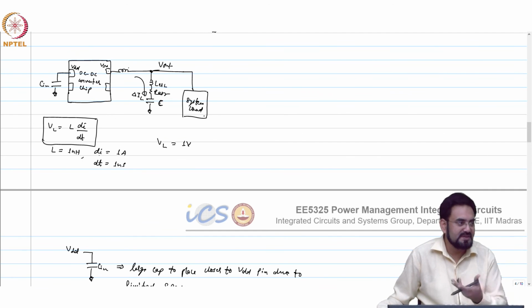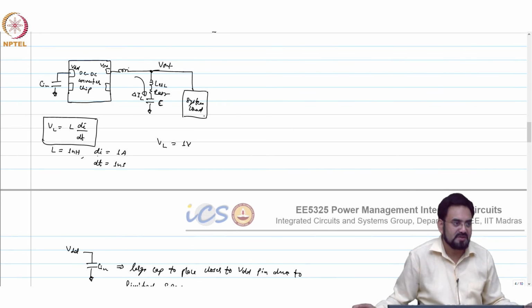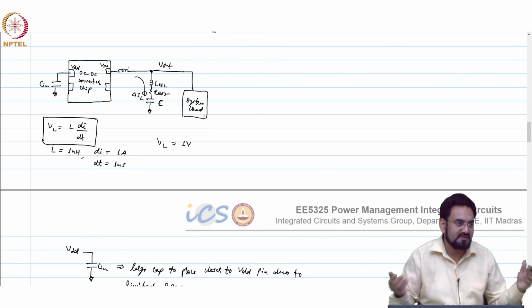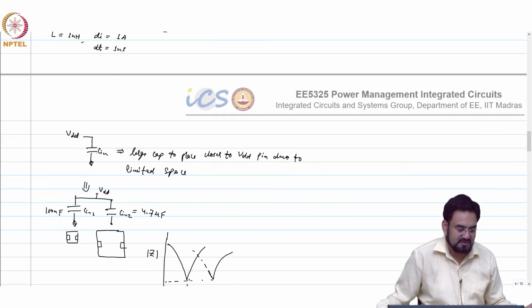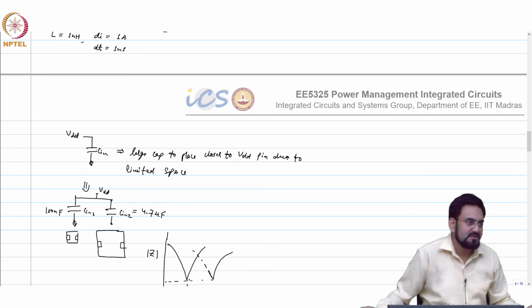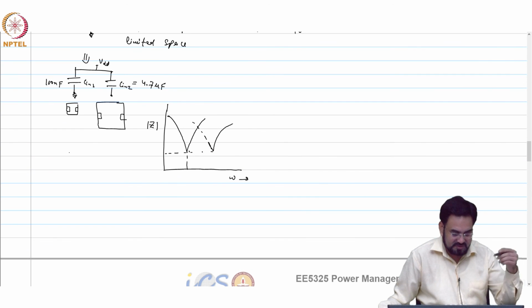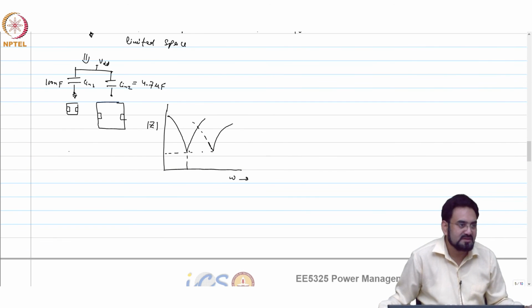By doing that, you will be degrading the efficiency and limiting your duty cycle also, because if your rise and fall time is more, that will limit your duty cycle, and your switching losses may also increase. If you remember the triangular one, that will stretch, so that loss will also increase. So we want that switch to turn on as fast as possible.